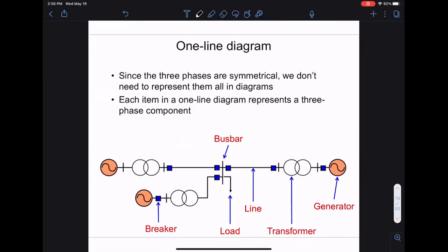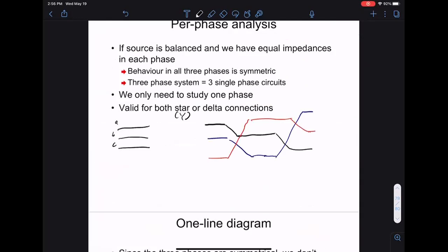Alex says, does that not increase the stray inductance? By stray inductance, you mean inductance to ground, Alex? No, I just mean the inductance through the wire when you're kind of looping it like that. No, so you have 3 wires. If you look at the actual inductance matrix, it's a 3x3 matrix, so it's 9 numbers. Transposing them like this just makes that matrix symmetrical. It's not necessarily higher inductance. So even though they're symmetrical, would it increase the overall inductance of the wire? Not necessarily, no.